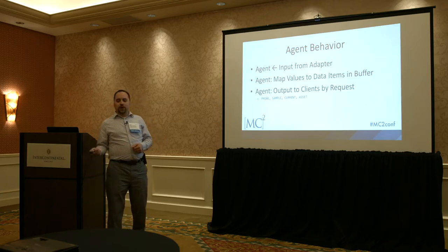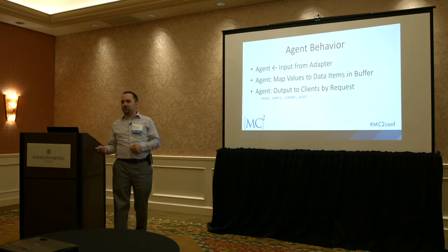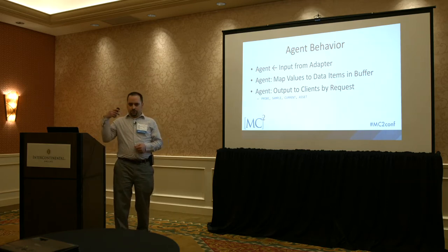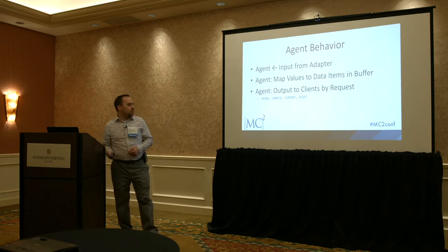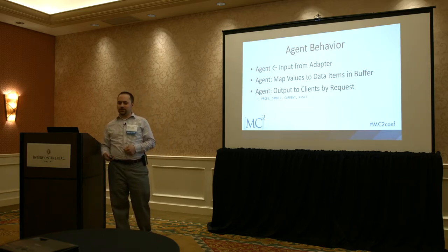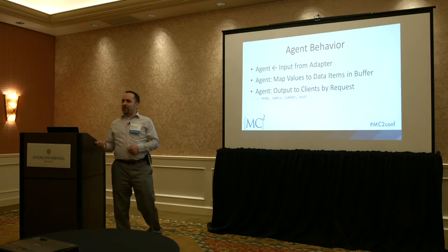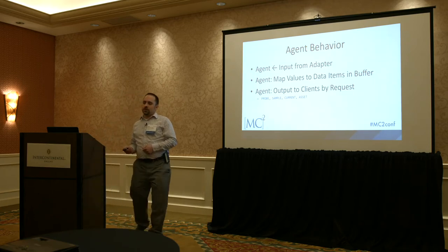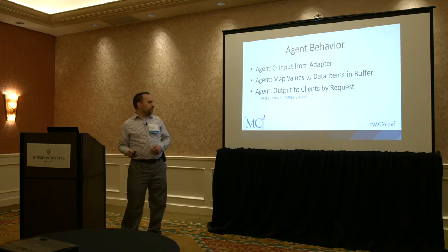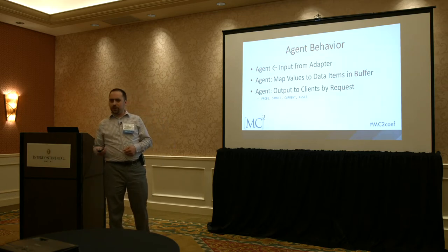And then they respond to the 4 verbs to provide data to a client, the 4 verbs being probe, sample, current, and asset. Probe is the device model definition. Current is every data item in that device model, so that's an exact moment in time. Sample gives you whatever's in the buffer from whenever you say you want to see the data, and is the heart of any streaming collection from the agent. And then asset deals in all kinds of different assets. Tooling is the primary one right now.